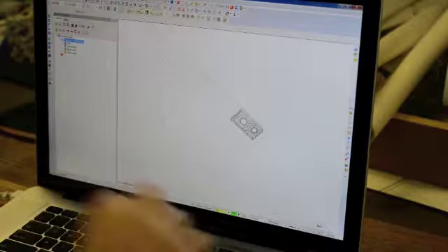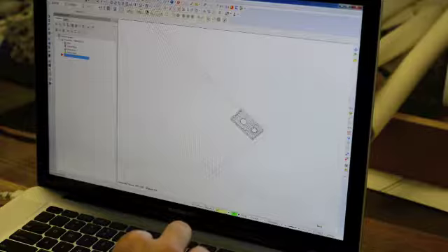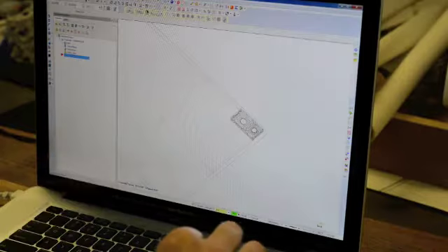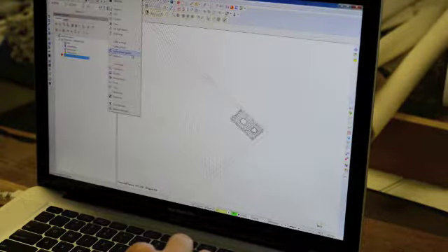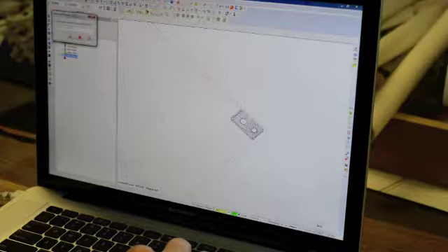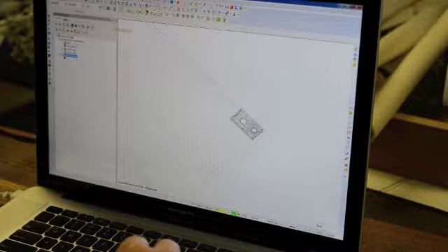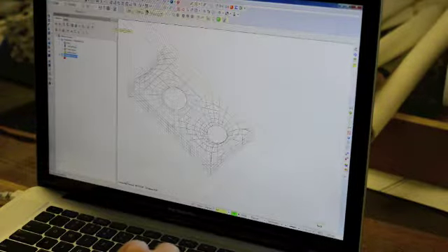Okay. So we have that done, then just click your mouse over on that red arrow, and so now we're sort of positioned there because the toolpaths are going to populate over here. So toolpaths, we are doing surfacing, so surface high speed. Check off yes. It wants a name, so you can just go with the default. Now it says select drive surfaces. So your drive surfaces are the surfaces you created in Rhino.